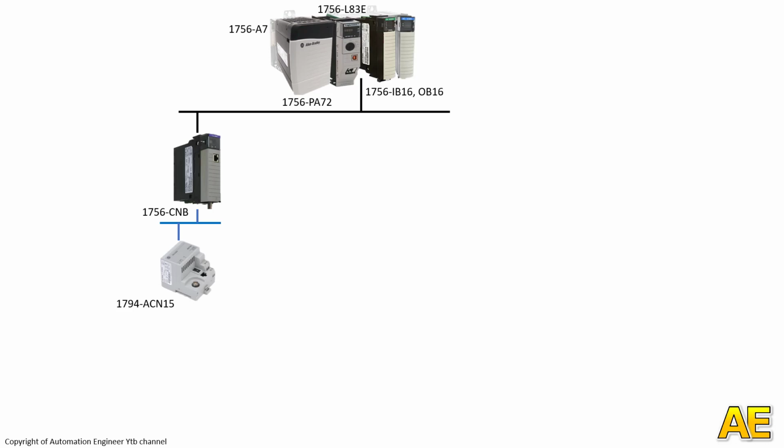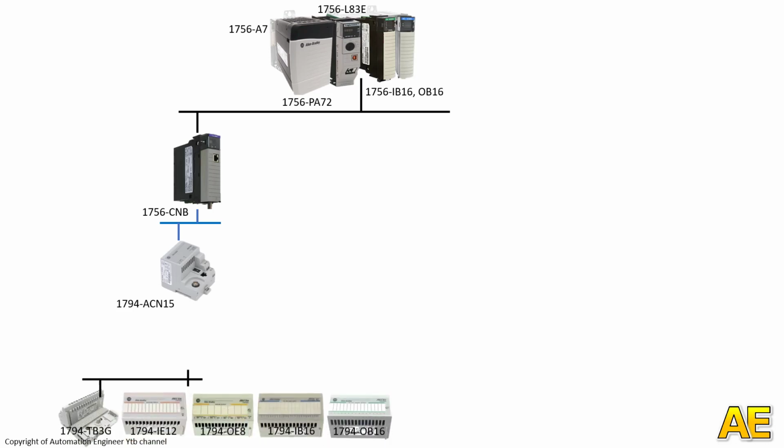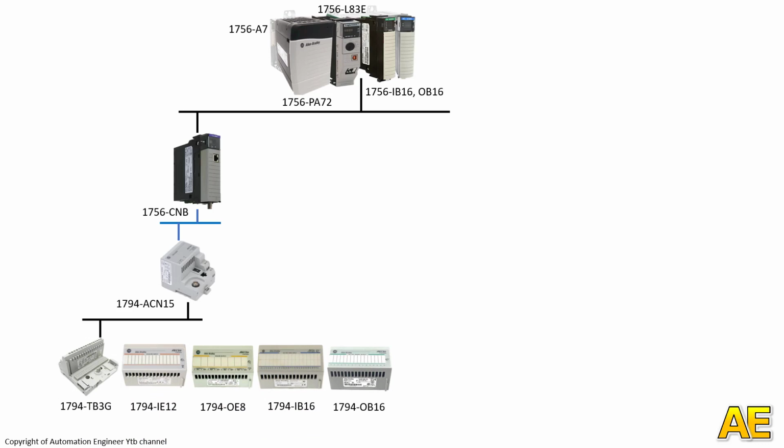Some I/O modules we can use: analog input 12 channels, 1794-IE12; analog output 8 channels, 1794-OE8; digital input 16 channels, 1794-IB16, and digital output 16 channels, 1794-OB16.